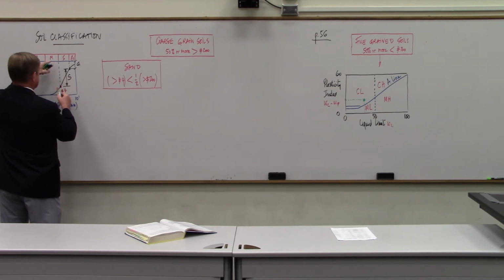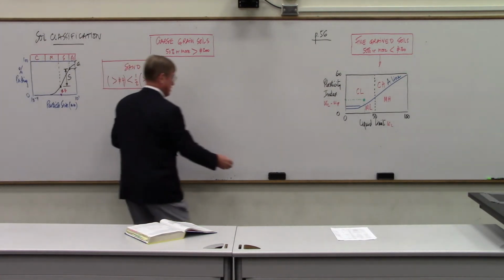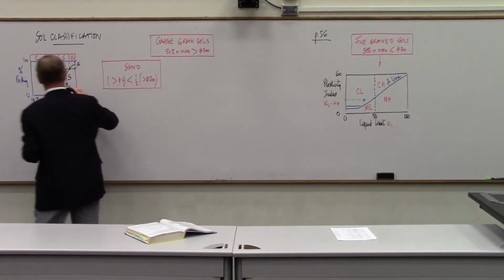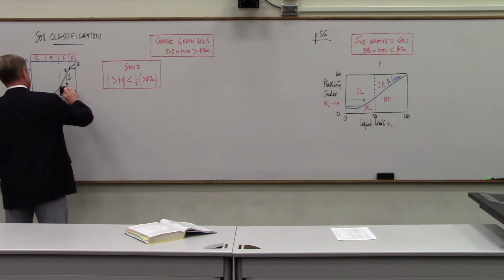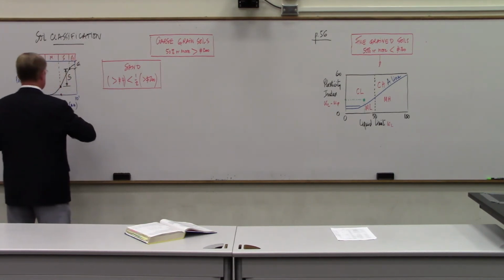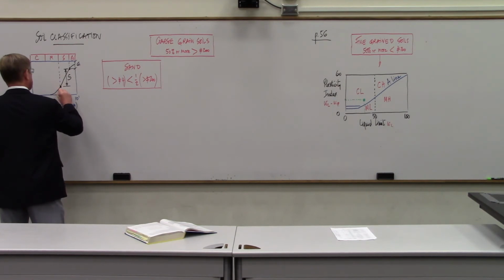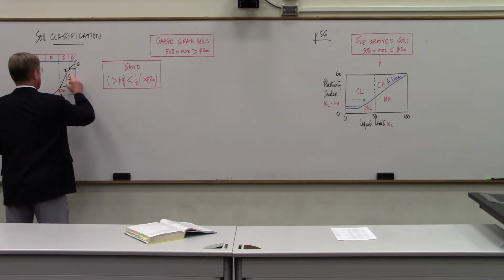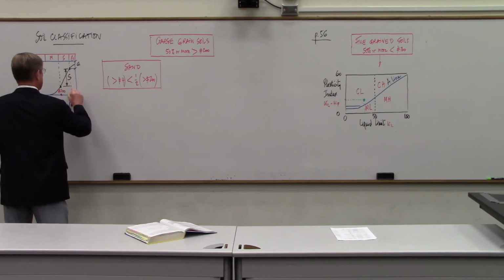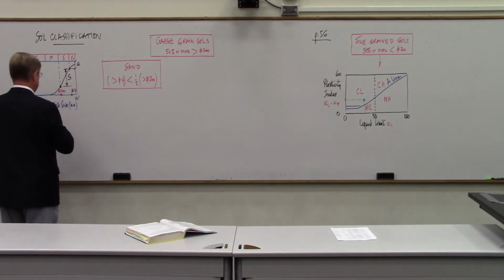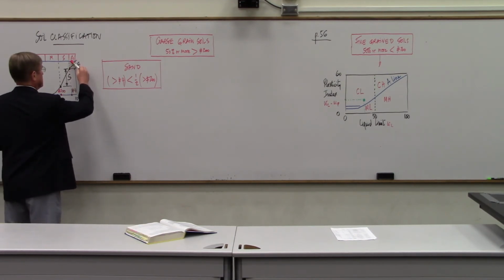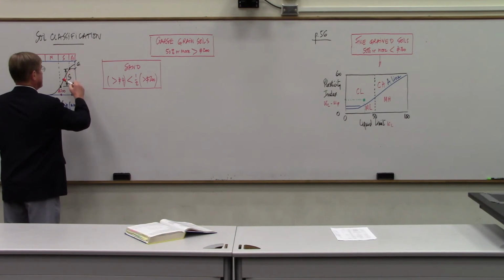Wait a minute, I made a mistake here. Number 4 is not here. This is number 200, because that's the separation. So this is number 200 right here, and this is number 4. So the portion larger than number 4, this one, is less than 1/2 of the portion passing number 200.